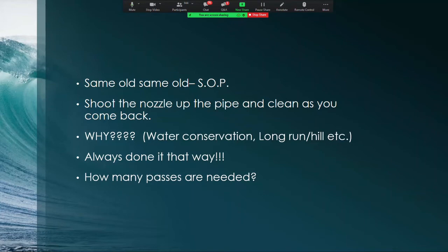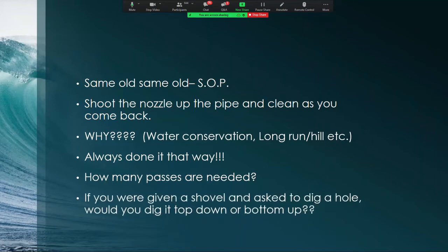When you clean pipe, shoot up the line quickly, and then bring back cleaning on the way back, quite often operators will either keep the pressure at the same level as it went out, or drop the pressure down to come back and pull the debris out. When you do that, the debris behind the nozzle will tend to overflow the nozzle because you end up with a pile behind the nozzle, which is going to necessitate going in and doing multiple passes. And doing these multiple passes, of course, has its own consequence.